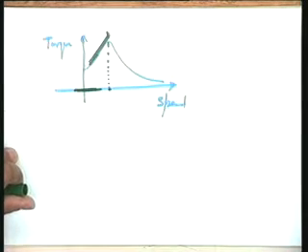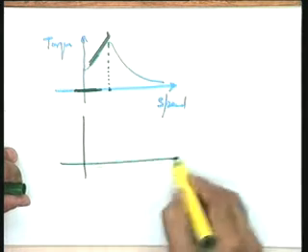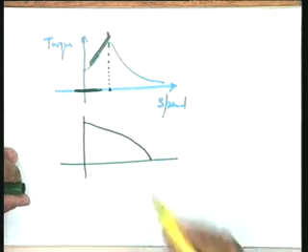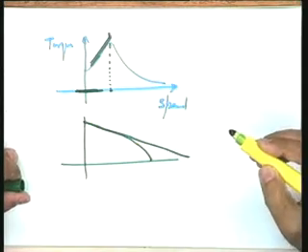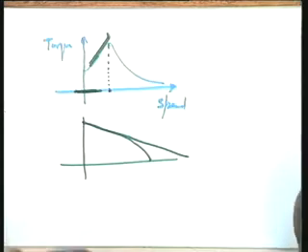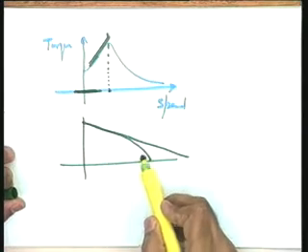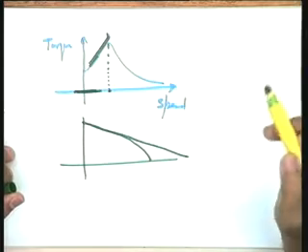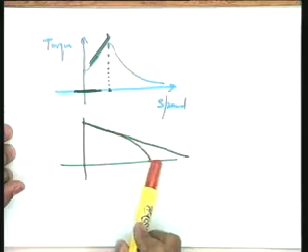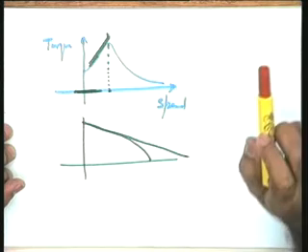By servo applications I mean position or speed control systems. What you need is this characteristic. You will recall this is the characteristic we had drawn, and in this characteristic the slope is always positive; it is never allowed to be negative. And how do you get these characteristics? You directly get these characteristics from the induction motor only by using high rotor resistance. So you see that a servo motor is nothing but an induction motor of high rotor resistance, so that the characteristic of a servo motor always has a positive slope.